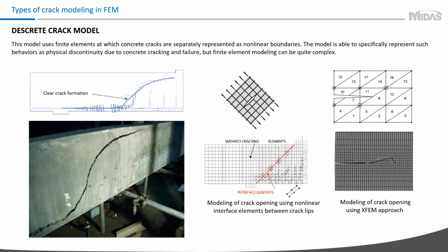In practice there exist two most used models of concrete fracture in terms of finite element method: the discrete model and the smeared crack model. The discrete model is especially suitable for simulation where the failure is governed by occurrence of a small number of cracks with a crack path that can be clearly predicted.